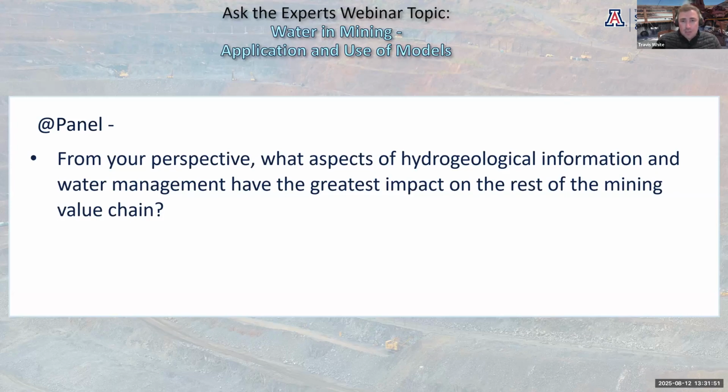What we've started doing is bringing all your hydrogeological fieldwork campaigns one stage gate earlier, and that's paying real dividends in terms of down the line cost savings, risk mitigation, and ensuring that you have enough time to get everything you need in place. One big thing that's going to become increasingly more relevant globally are the permitting constraints. So ensuring that you have good quality baseline information available can make your permitting a lot easier as well.